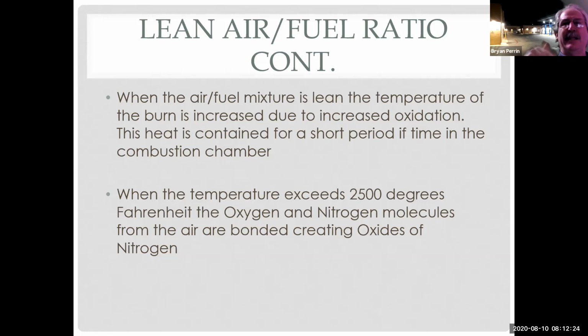And that's why lean mixtures create NOx up until we get to about 16:1 air-fuel ratio. After about 16:1 air-fuel ratio, we start misfiring. When we're misfiring, we're not burning all the hydrocarbon, therefore resulting with the raw gas still in the combustion chamber of a cooler mixture, and NOx starts to drop. And we'll see that on the following slides.